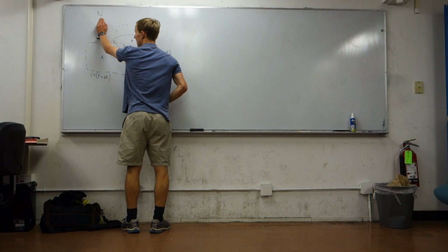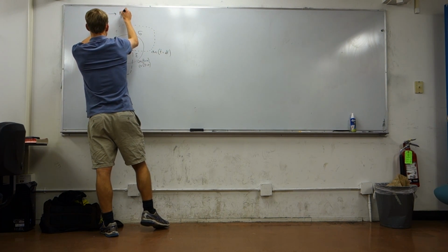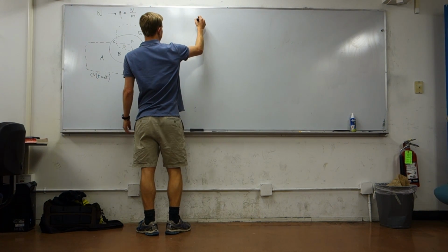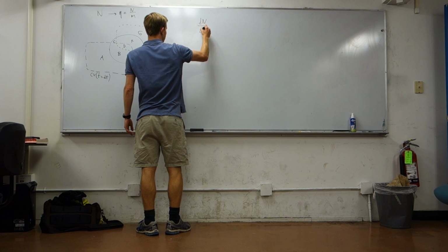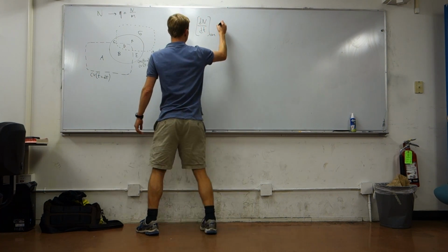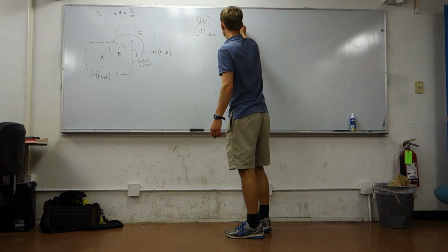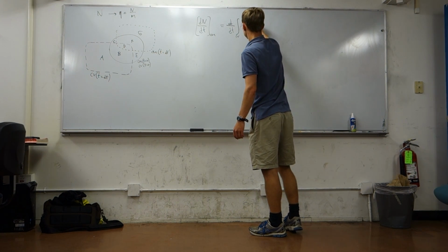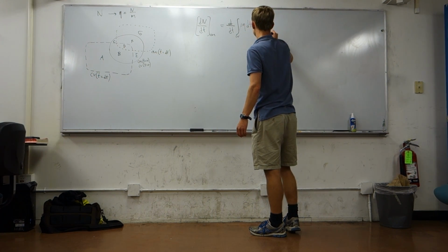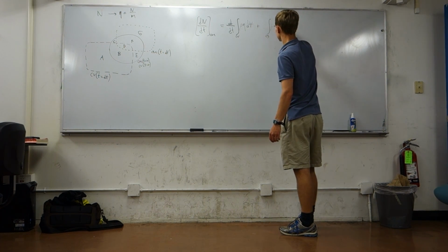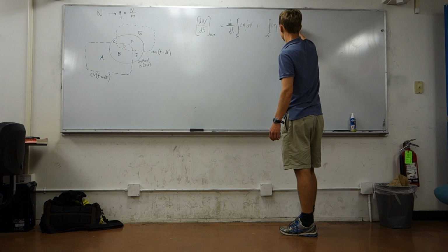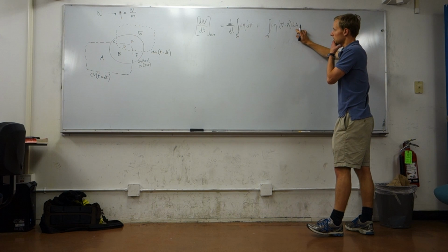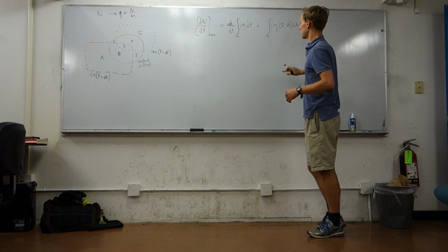So if our quantity we're conserving is N, we're going to conserve the specific quantity eta, which is N over m. This is the intensive property eta. And so we know that dN/dt in our control mass is the rate of change of eta in our control volume plus the flux terms: the integral over the control surface of rho eta times the dot product of the velocity of stuff leaving the control surface with the surface normal times the area. Okay, so let's talk about what each of these terms mean a little bit further.